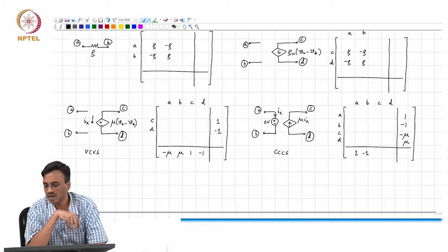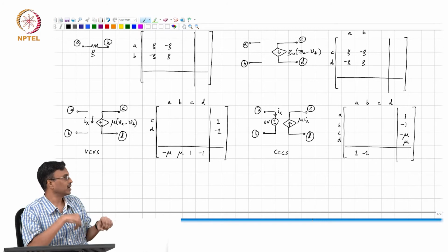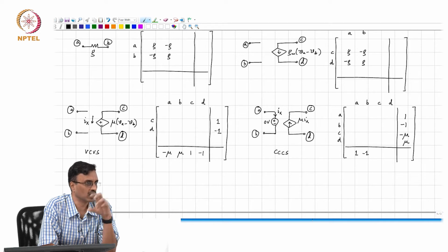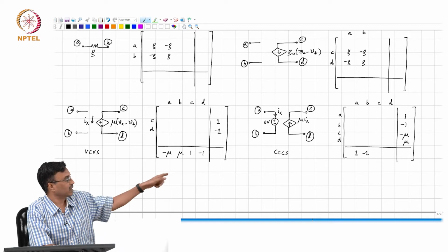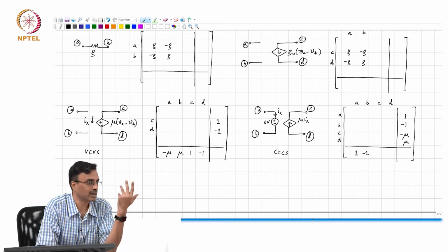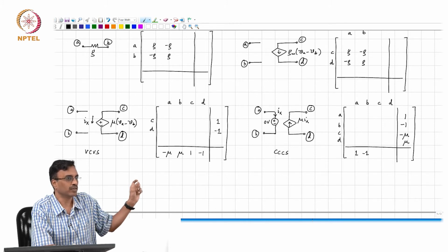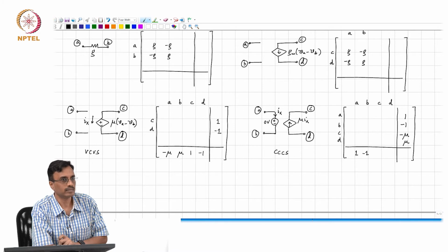The assumption in a circuit simulator is that you always measure current through a 0 voltage source. It is also likely that you can have an arbitrary branch current and make this mu times Ix a multiple of that arbitrary branch current, in which case it's straightforward to artificially introduce a 0 voltage source and add an extra node there, and the formulation just works. Is this clear?